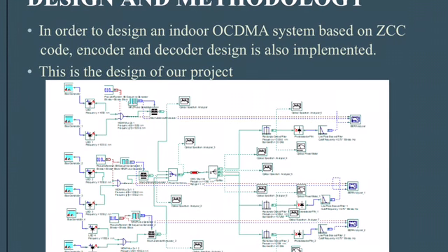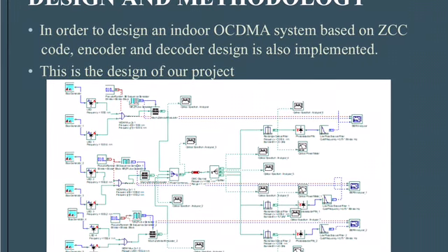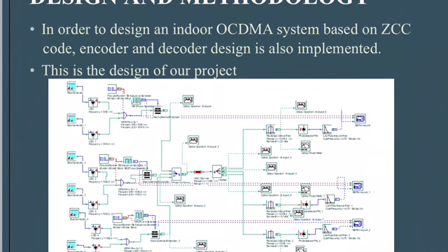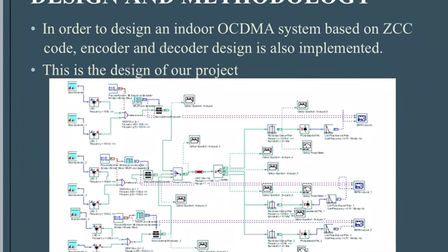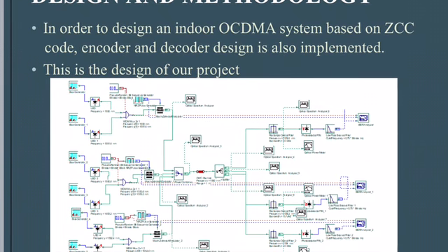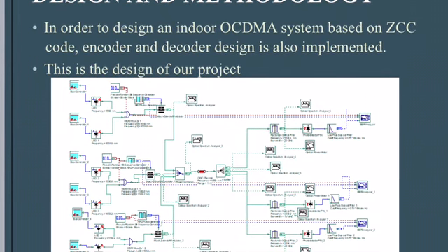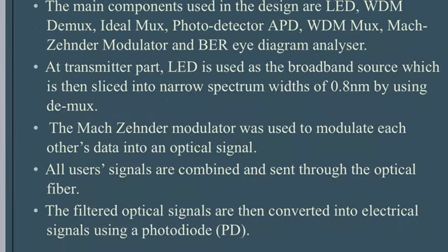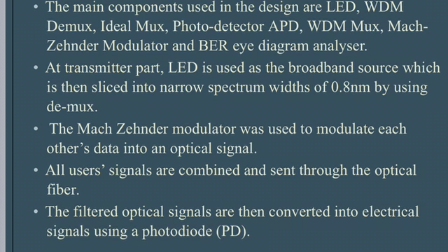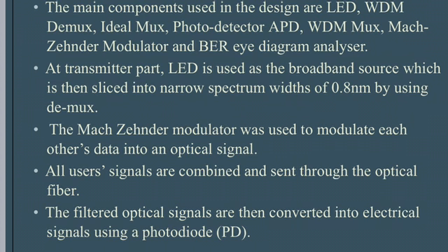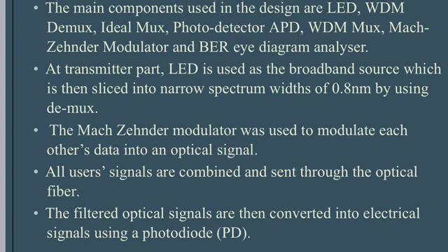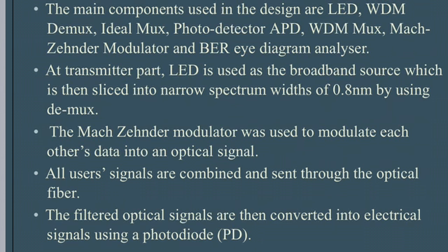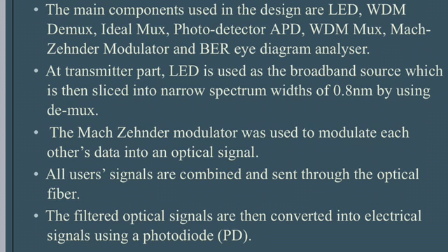Design and methodology. In order to design an indoor OCDMA system based on ZCC code, encoder and decoder design is also implemented. These are our simulation. The main components that we use in this design are LED, WDM, DMUX, PIN photodetector, WDM MUX, Mach-Zehnder modulator, and bit error rate eye diagram analyzer.